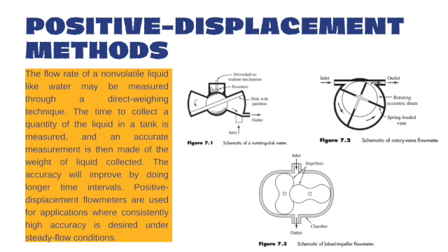Water enters the left side and strikes the disc that is mounted. The fluid moves while the disc wobbles about the vertical axis. In Figure 7.2, the rotary vanes are spring-loaded so that they continuously maintain contact with the casing of the meter. This eccentric drum rotates and the fluid eventually finds the exit.